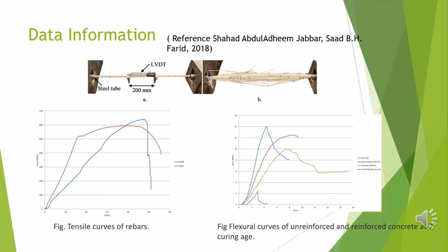For other considerations, in the second graphic of the flexural curves, it's possible to identify the steel as the blue line and the use of GFRP in different compositions in the red, blue and green lines. The green line is safe for construction because it shows good behavior around the sections. In this case, the fibers contribute flexural capacity to these elements.